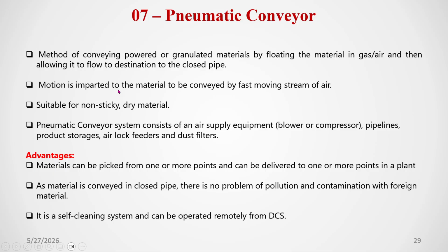Motion is imparted to the material to be conveyed by a fast moving stream of air. So high velocity air is introduced. It will take the material through the pipe from one end to the other end.